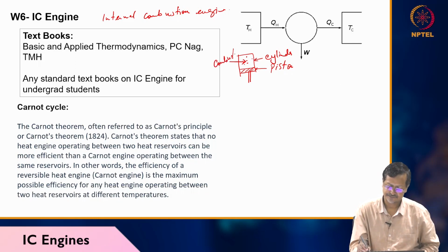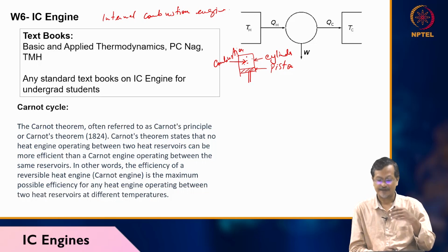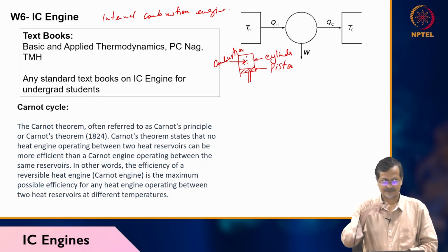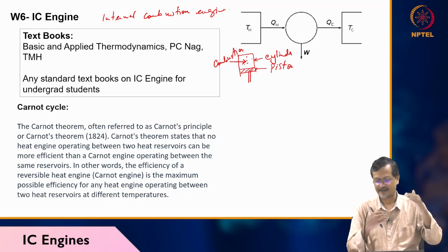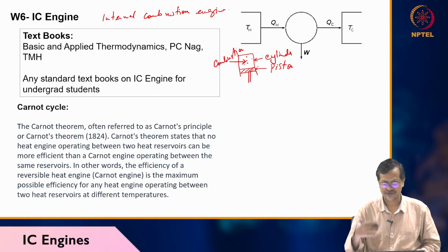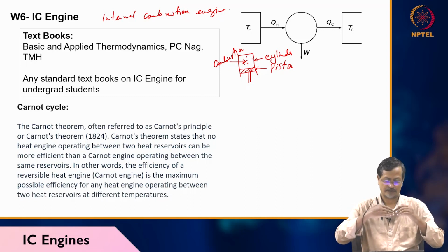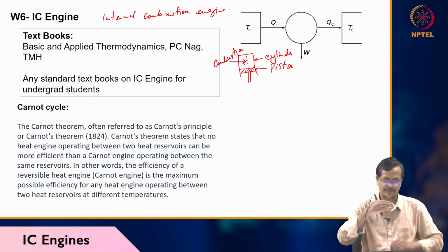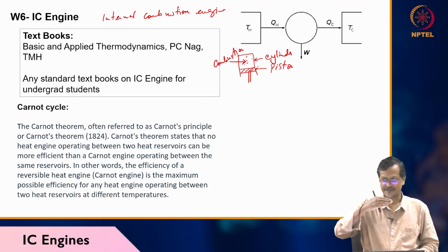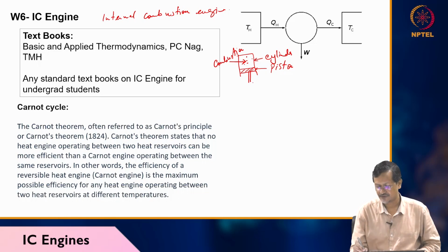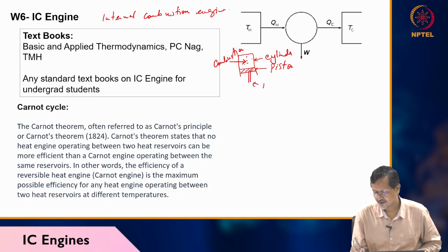Combustion or reaction: fuel and air you take inside this cylinder, combustion will be happening, and this will be creating high pressure gas. That high pressure gas will be pushing piston down, and because of this piston down movement, again another activity will be there, like piston will be moving up and down. So one reciprocating action will be happening continuously in piston. So that will be giving your rotary motion in a shaft. So this will rotate shaft.